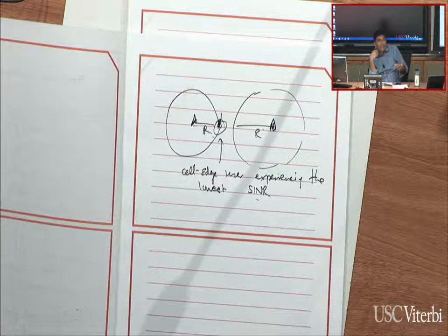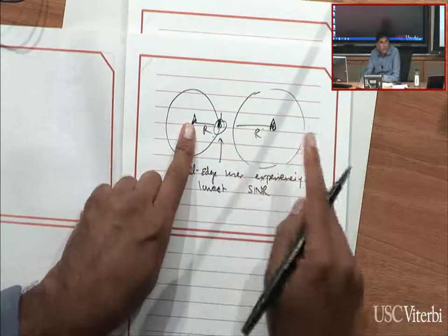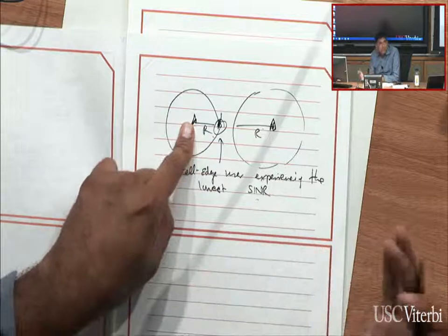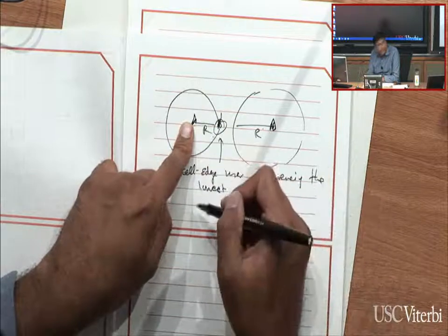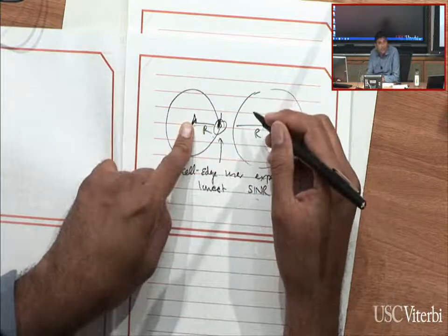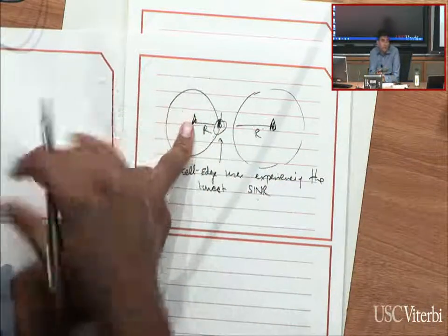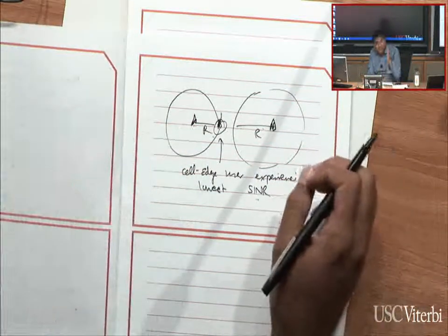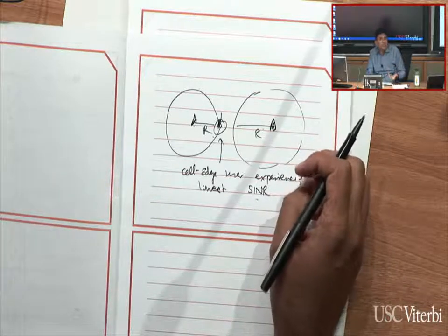And so we're asking this outage probability question: what's the probability that this SINR is so bad that I can't even communicate? If these two base stations intuitively were too close, we won't be able to communicate. But adding in this variation in the channel quality is actually complicating our life, because now we're increasing the chance, on the one hand, that the signal might be dropping, and we're increasing the chance that the interference might be high. At the same time, at other times, it might be the opposite, meaning the signal might be strong and the interference might be low. But from the probability of outage perspective, the number of times in which I drop below the threshold when I'm unable to talk on the phone, that's the thing that's of interest to me.